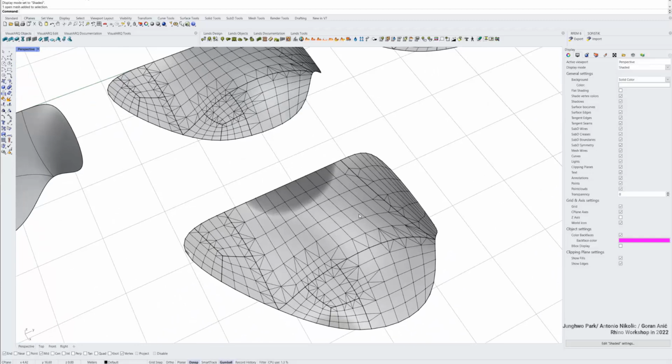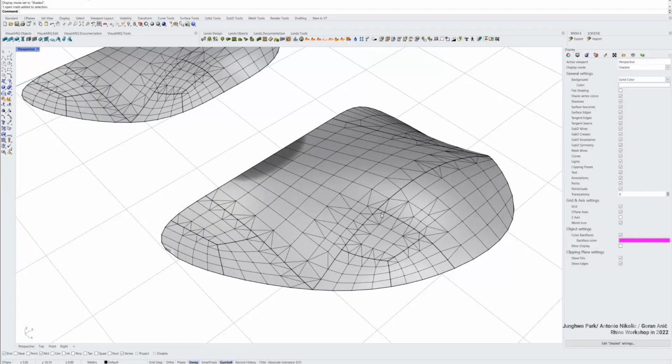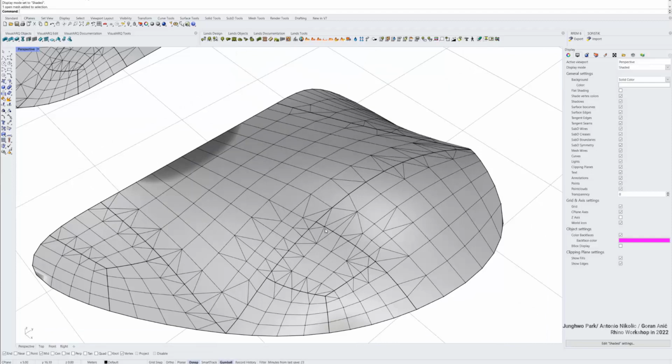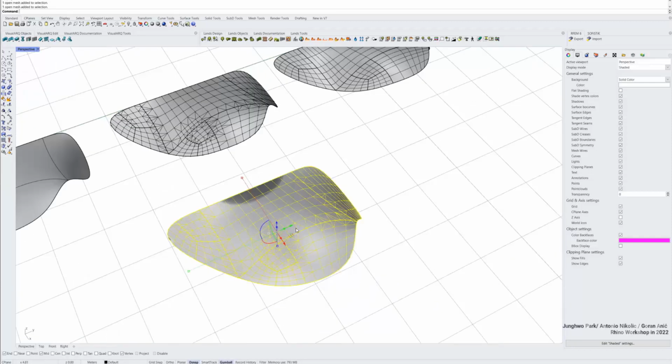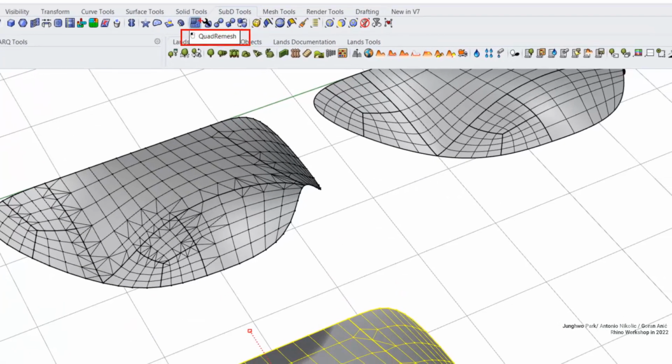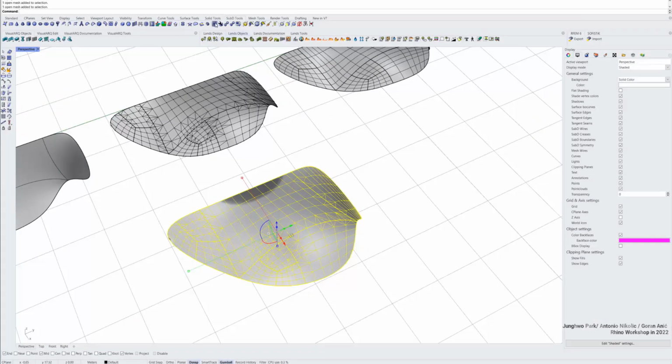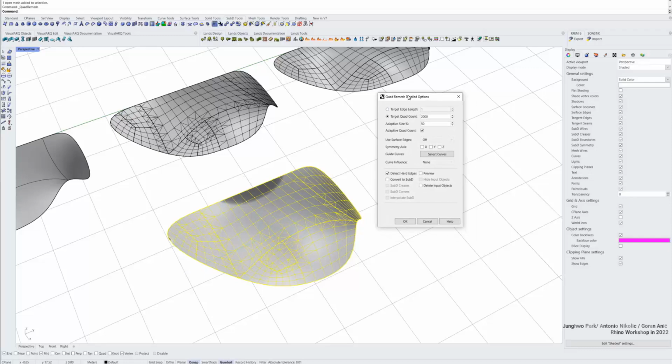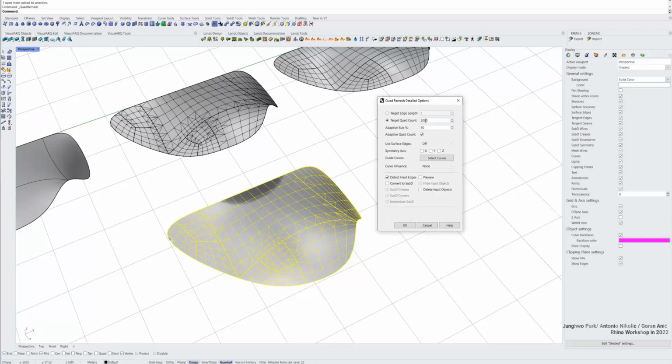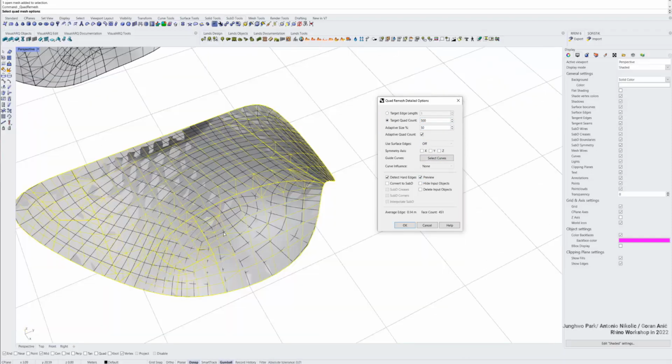Okay. And we can recreate this mesh structure as a quad mesh. In Rhino 7 there's a command called QuadRemesh. On the sub-D tool the command was called QuadRemesh. This command becomes really interesting. I'll click, and we can control the target polygon number, I mean the quad count number. I'll make it maybe 500, and we can see the preview actually, and that's reconstructed